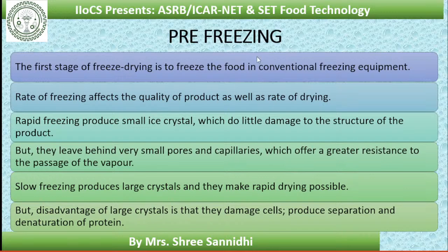Yeah, first step is pre-freezing. The first stage of freeze drying is to freeze the food in conventional freezing equipment. Rate of freezing affects the quality of product as well as rate of drying. So rate of freezing is how fast we freeze.